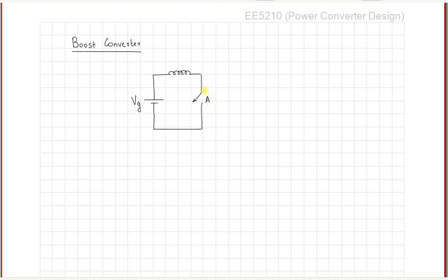When the switch is open, the inductor will try to continue its current, so we need to have a switch which will conduct in this direction, and then this energy stored in the inductor can be dumped to a capacitor, which will then provide you the voltage, which is a stepped up version of the input voltage. So this capacitor is C, this is your load resistance, and that is the inductance. This switch can be labeled as B.